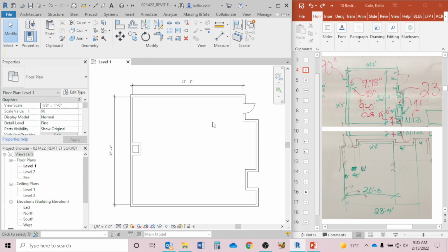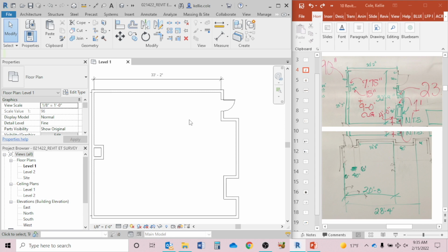So we're going to utilize the same method that we used when we laid out the tape in the classroom. By using the running dimension, when we laid out the tape and read the numbers, we found the door jamb, if we look at the bottom image on the right, at 6 inches, other door jamb 40 inches, wall recess 6 feet. All of those numbers were taken off the 0 mark, that front wall of the tape. We're going to offset or copy using that same running dimension method when we draft. So hang with me here. This can become tedious.